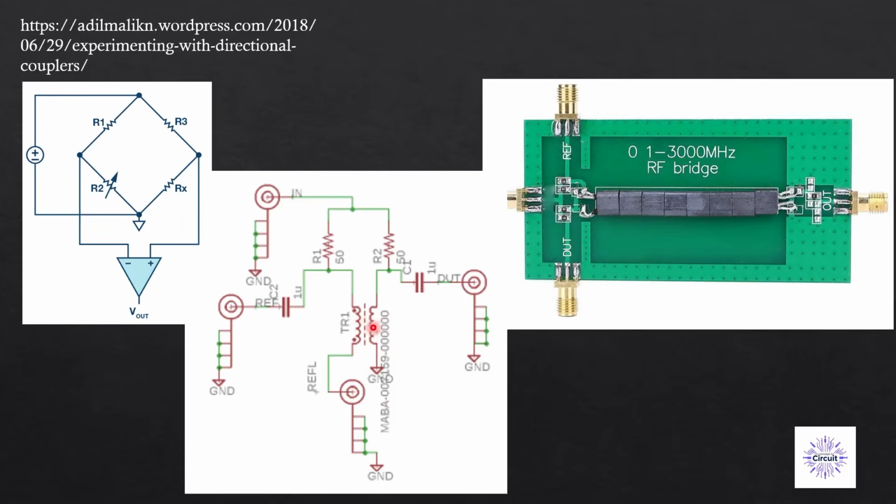And these baluns are used in many applications in RF design, either in discrete implementations or integrated versions. So this balun, which is essentially a type of RF transformer, can get connected to our differential voltage here and output the single-ended version. The other side can be defined as ground.